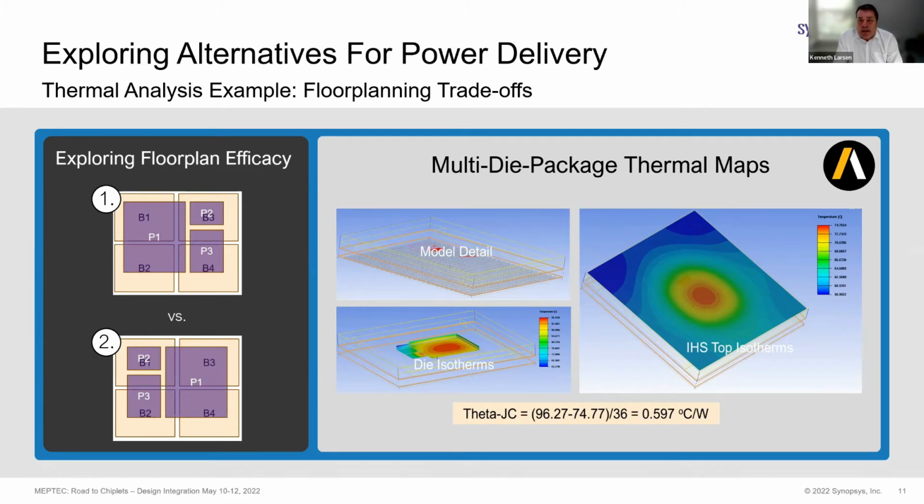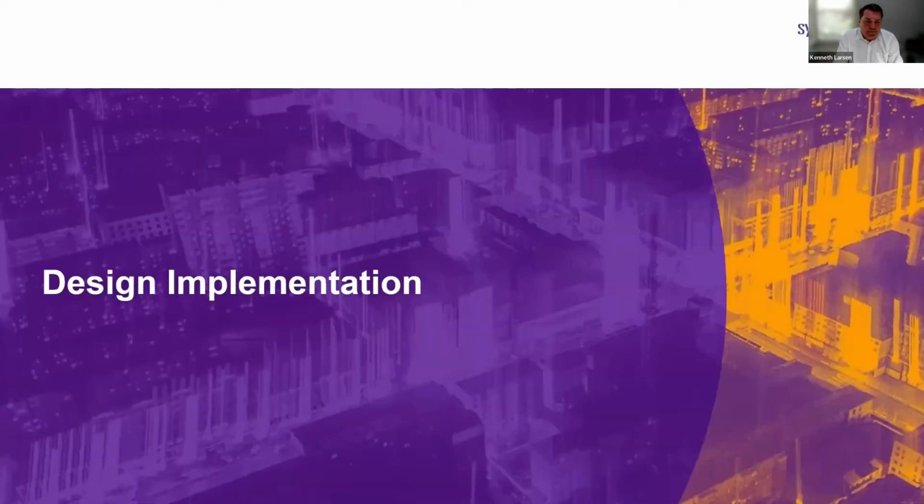And we're using Ansys' excellent Electrothermal to give us insight into consumption, where we may have to increase the density of TSVs to get sufficient power, or maybe use the TSVs as dummies to transfer heat away from certain areas of the design. So there are many options that we're enabling our customers to take.